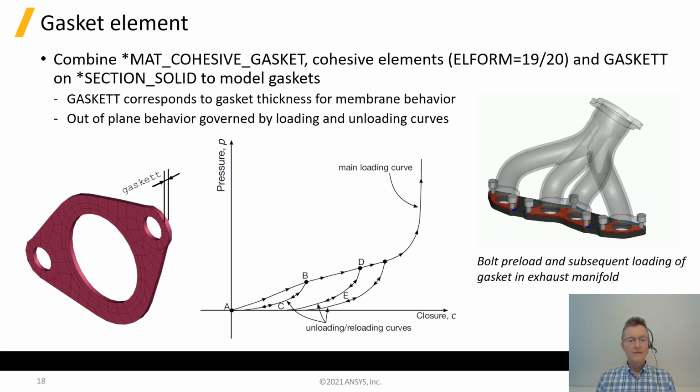The material behaves somewhat like a foam in that it can crush and recover at small to medium strains here, but then at higher strains it locks up. And the user supplies load curves to define the loading and unloading behavior.